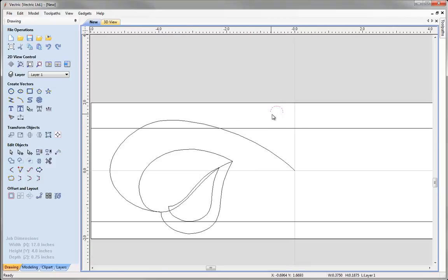I'd like to make another cross section from this vector. It's just a smaller one, so we can create a variation in the shape of the stalk. So with that selected, I'm going to select that again. I'm going to press Ctrl to create a copy and Shift to scale that in proportion. I'm just going to bring that down like so.